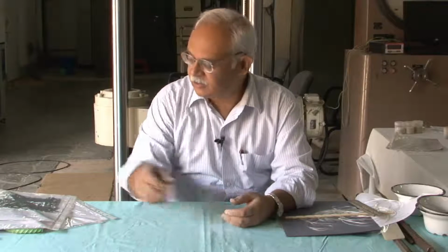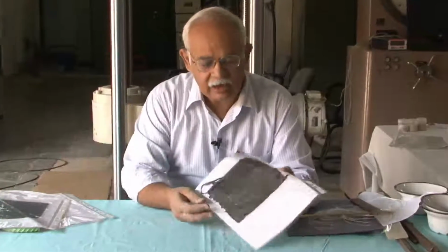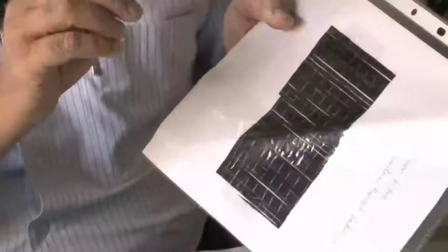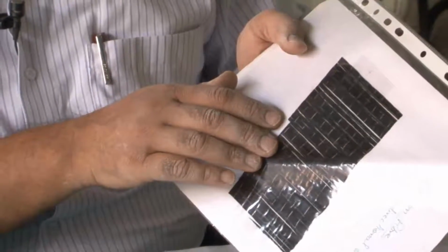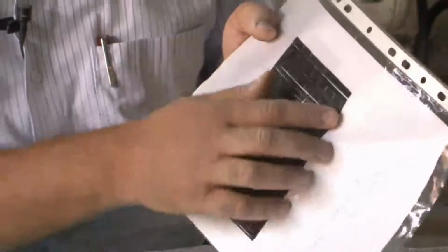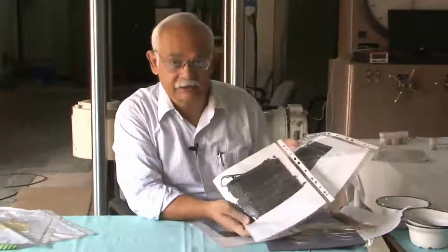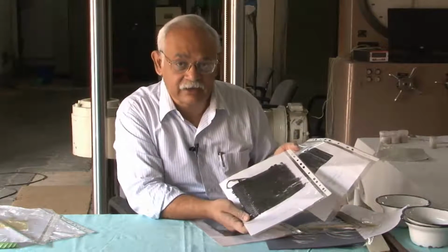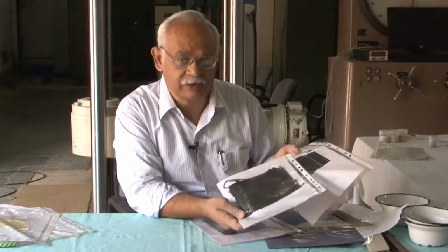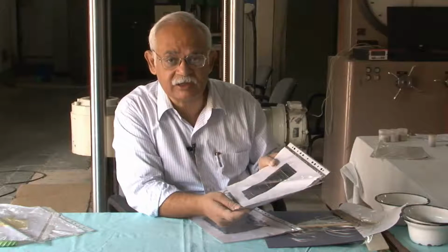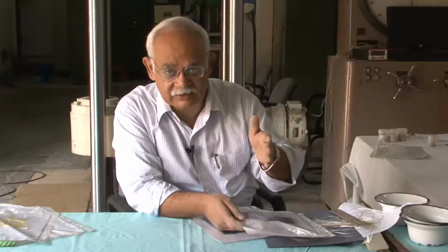in different forms. For example, these are carbon fiber woven fabric. A similar fabric is a random mat in carbon fibers like this. In a unidirectional carbon fiber fabric, all the fibers are aligned in one direction. In the case of a woven fabric like this, they are aligned in both directions. So, we get reinforcement action in both sides. In this case, we get reinforcement action only in the one side, that is the direction in which the fibers are aligned.